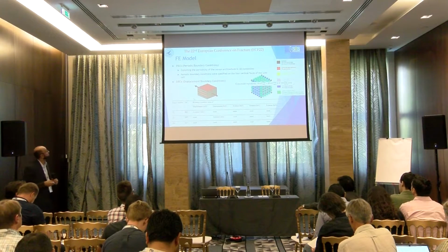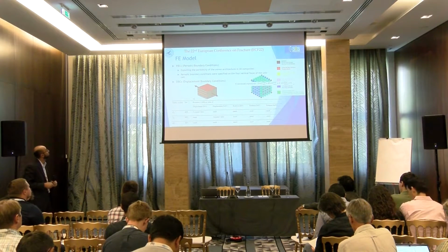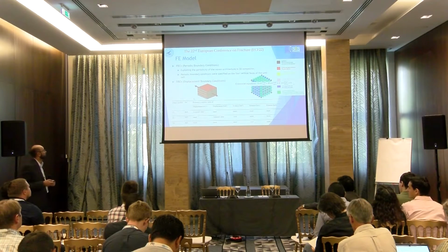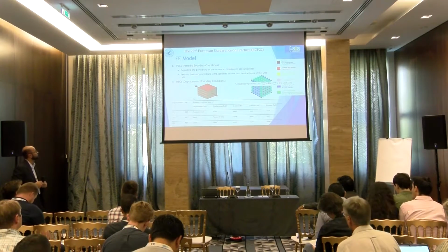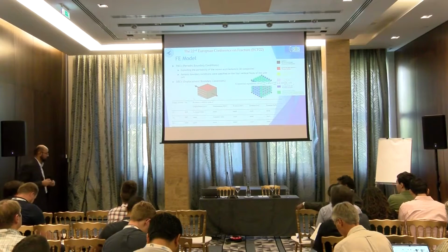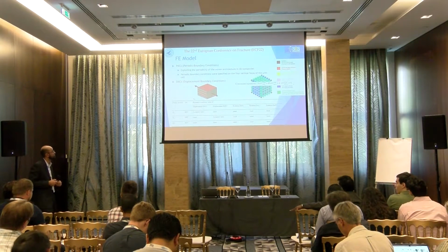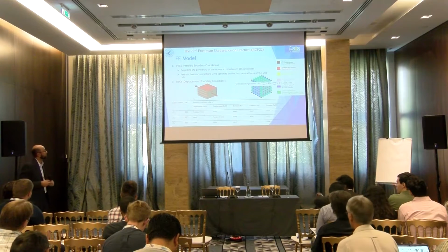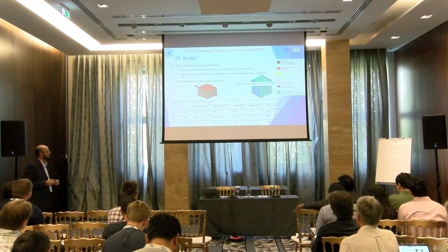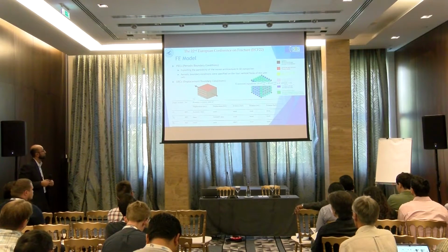After defining the periodic boundary condition, displacement boundary conditions have been defined. If we are examining the elastic moduli in direction 1, the displacement degree of freedom has an assigned value through this equation, and all the other values are unset, so it is free to move in all other directions, and similarly for direction 2 and direction 3.